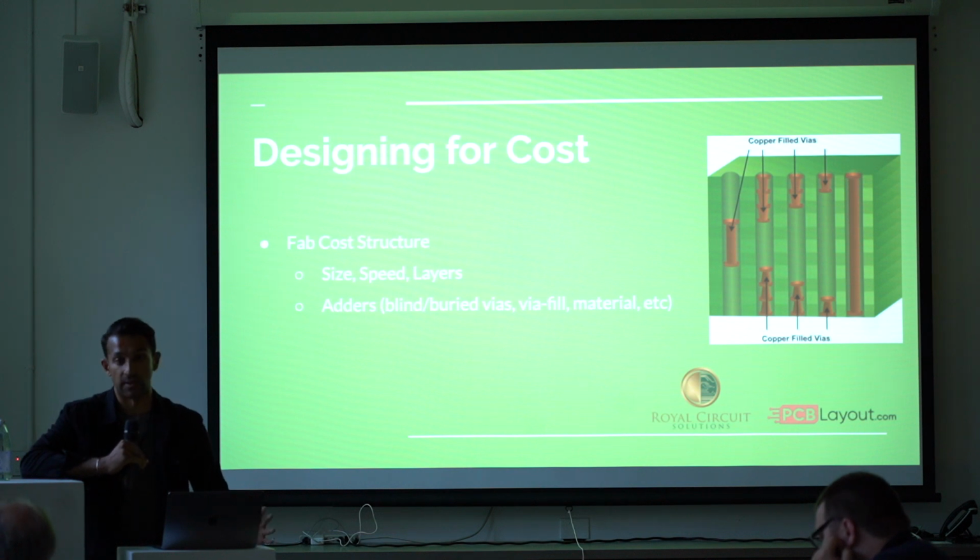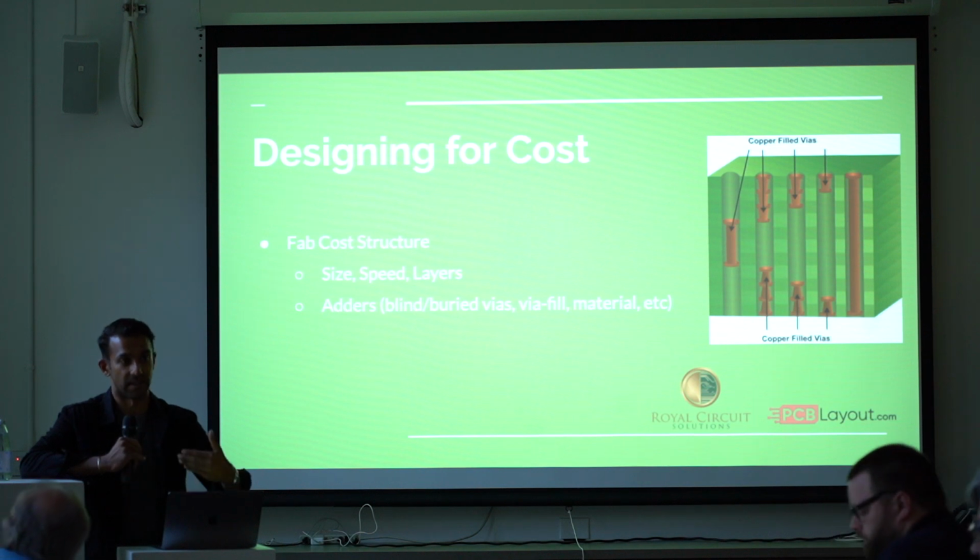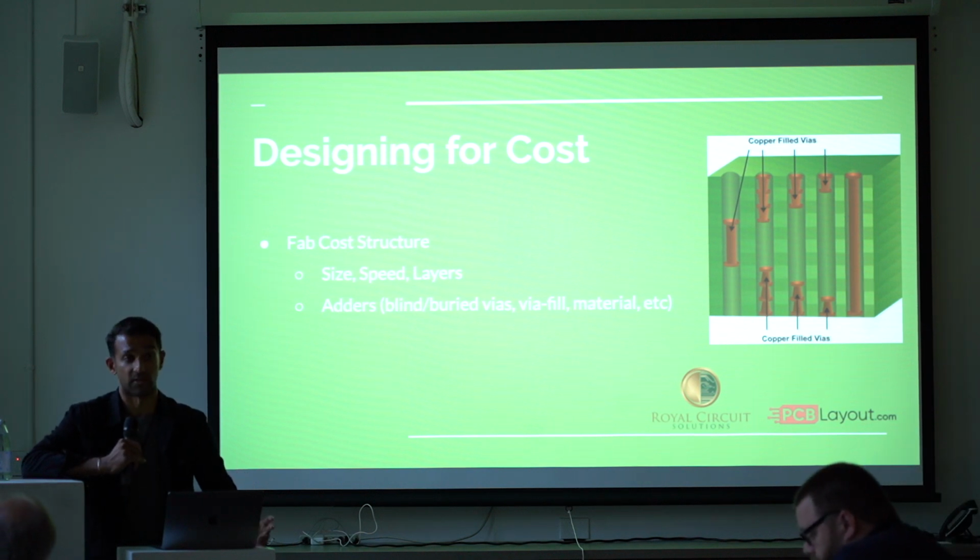The good thing about us, we don't use stencils. And we use really, really high-speed precision trace printers. And these things will get the exact amount of solder deposition on every single pad. That'll give you a different amount of solder on a BGA pad versus like a 0402 resistor. So you kind of get the right amount going, and it's way faster because it's all software driven.